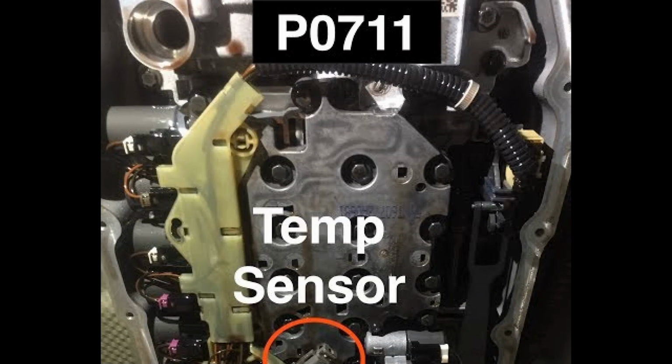The PCM supplies a 5V reference signal to the sensor and measures the voltage drop in the circuit. When the transmission fluid is cold, the sensor's resistance is high and the PCM detects a high voltage signal. As the fluid temperature warms up to normal operating temperature, the resistance decreases and with it the signal voltage.